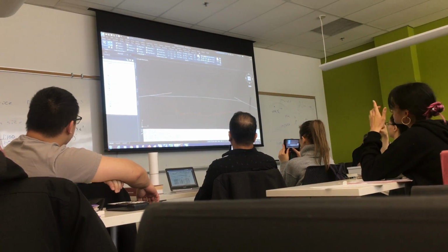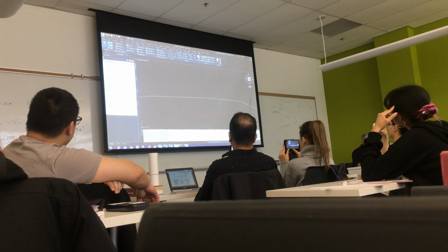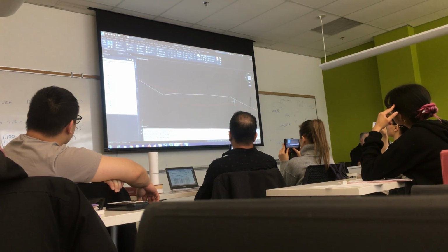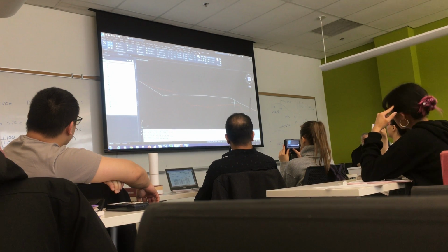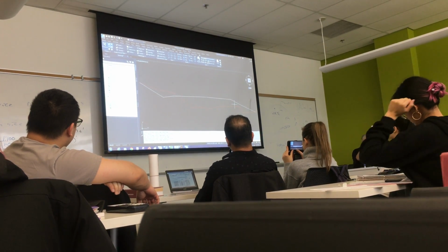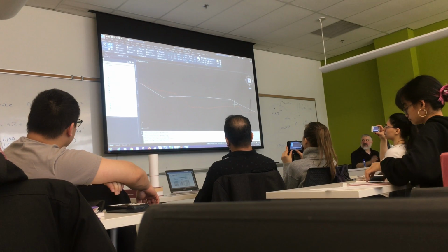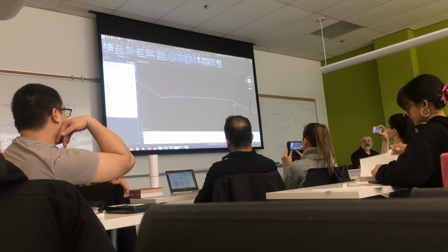I'm going to trim this. This is called the subgrade. That's the shape of the ground before you bring in your granular material, your base, subbase, sorry, your subbase, your base, and then your two asphalt layers, right? So you have to build this out of the native material first.